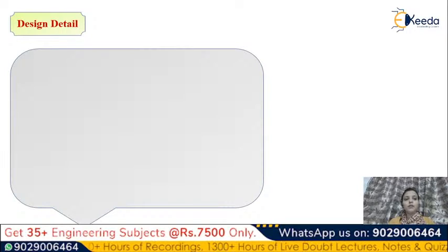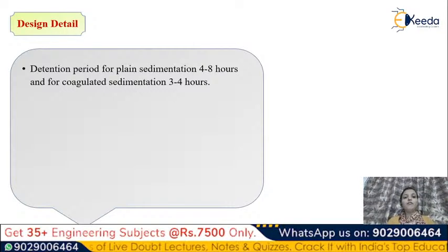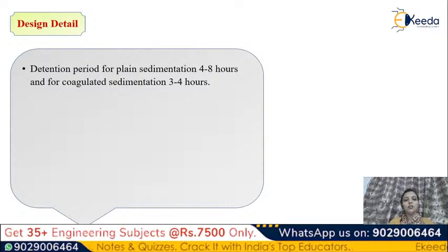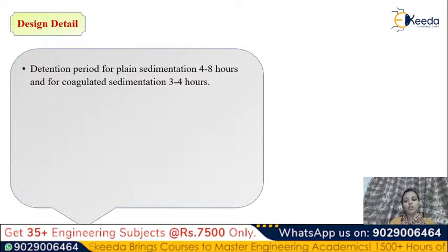So these are some design parameters that we should follow at the time of design of a sedimentation tank. The detention period for a plain sedimentation tank should be maintained at approximately 4 to 8 hours. That is also an important point, because sometimes they ask it in MCQ-type questions. What is the detention period of a plain sedimentation tank? That should be 4 to 8 hours. And for the coagulated sedimentation tank, it should be reduced, approximately 3 to 4 hours.